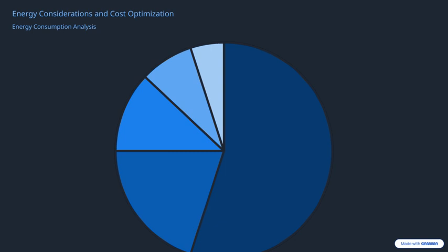So, how can we address this? One key strategy is aeration optimization. Advanced control systems, such as demand-based aeration and precise dissolved oxygen control, can cut energy use by 15 to 30% without sacrificing treatment performance. Think about installing variable frequency drives, profiling oxygen levels in different zones, or using ammonia-based aeration control. These are all ways to fine-tune the process and save energy. High-efficiency blowers and diffuser maintenance also play a crucial role here.